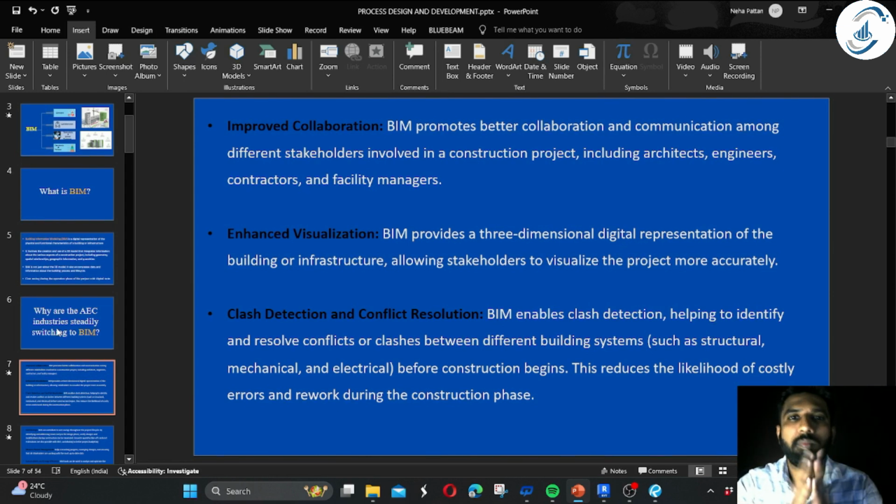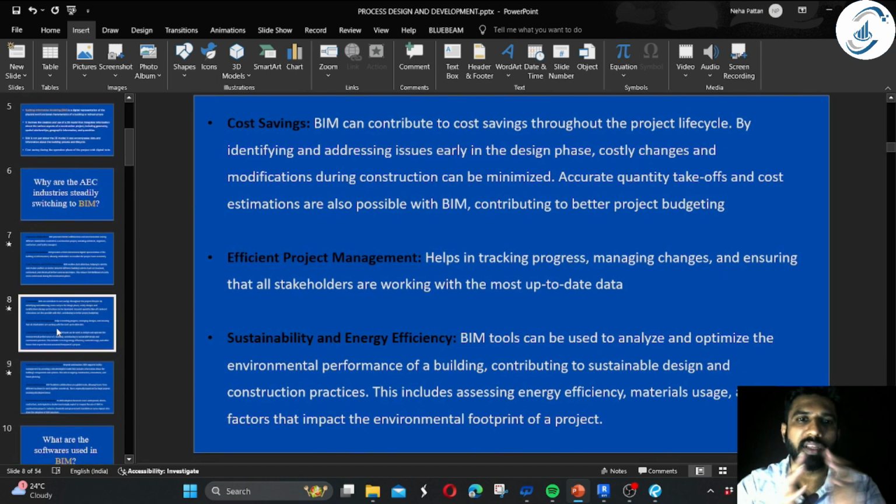But when we use building information modeling and do the coordination in 3D, such errors can be spotted even before starting the construction. So using BIM, we are eliminating a lot of errors. What do I mean by rework? During the construction stage, let's say I had to bring down the height of my ductwork so that it doesn't pass through the beam. That is rework. So we are avoiding the rework when we are using building information modeling.